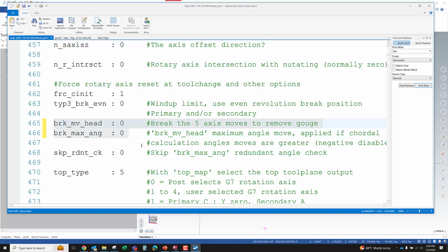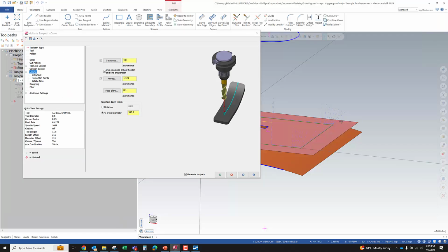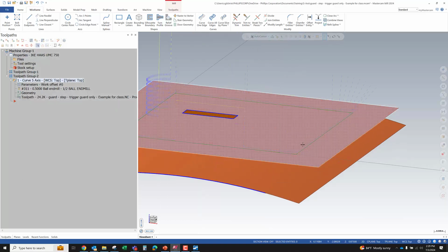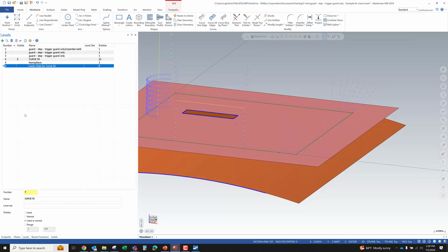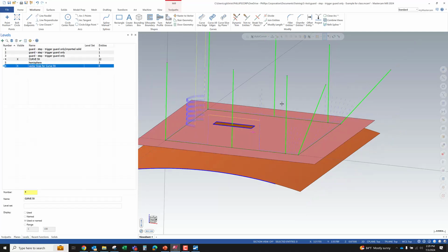So these guys will get you right here. Now, if the quality of the vectors is not quite right, and that's why you're getting weird jittery motion, then I would look at the quality of your geometry. So, for example, if you had a bunch of tilt lines that you were using, are all the tilt line definitions good? Is one of these rotated either in the front or the right side plane slightly?